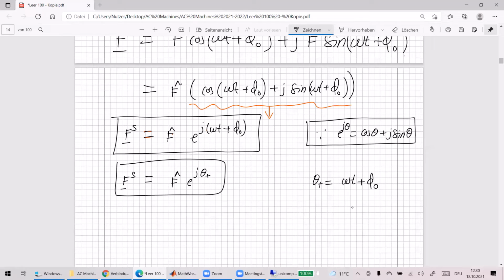Now I have a question. When I say DC, it is basically this thing, right? This is your amplitude, this is your DC quantity which we want to know. Because of this e power j theta, we have an AC component, which is your cos theta and sine theta. We just want to get the DC component, we don't want the AC component. So what can you do to make this DC? You can multiply with something or divide with something.